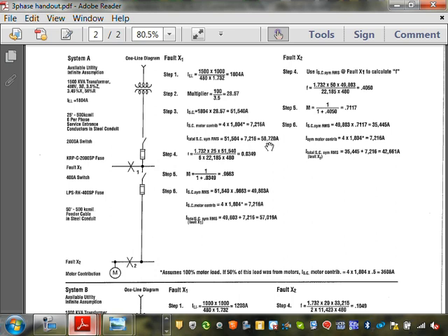Then this is called the F factor. Divide to find the M factor, which is do this math, and then multiply it by the available short circuit, and the current coming in will be knocked down because of the impedance of the cables. So that 49 will be right here. Add to it the motor value, and that total at this point here will be 57.0. Contribution from the motor and choking from the cables. So that's how you do this calculation.